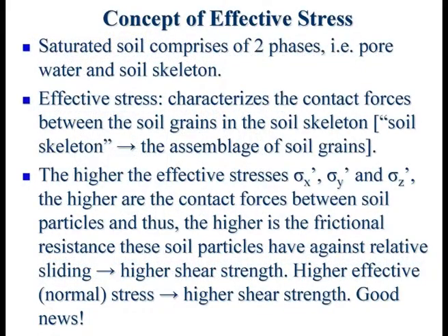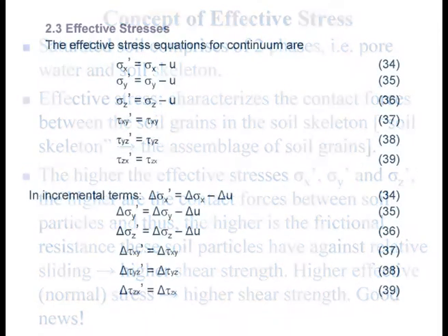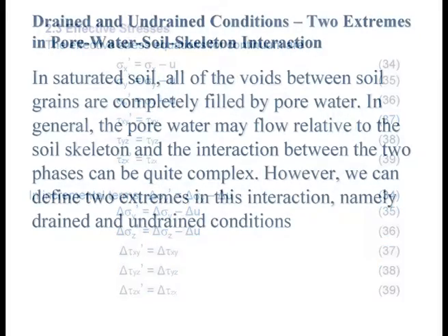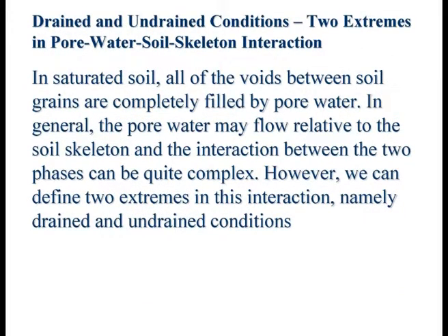And then we went into the concept of effective stress. This is the full set of the effective stress equation. The main thing is that water carries no shear stress. Water carries no shear stress. It only helps to carry the normal stress. So in a sense, it helps to reduce the effective stress, but it doesn't do anything to the shear stress. In fact, in most cases, we usually do not talk about effective shear stress. We talk about just shear stress, because effective and total are one and the same thing.